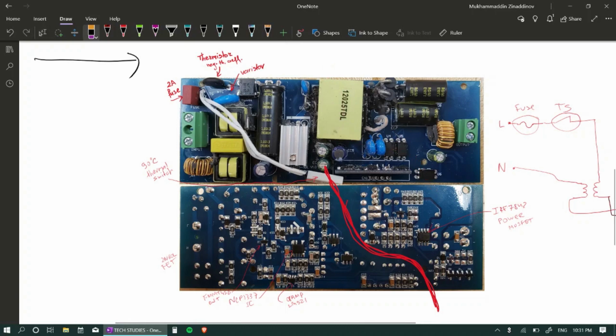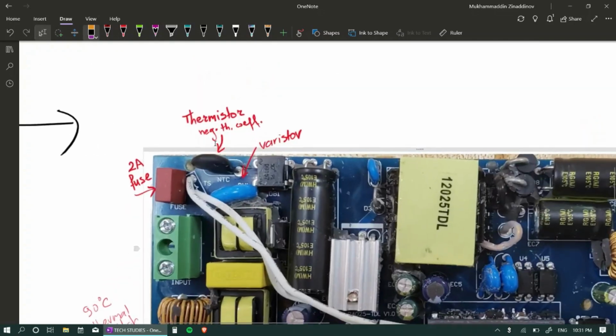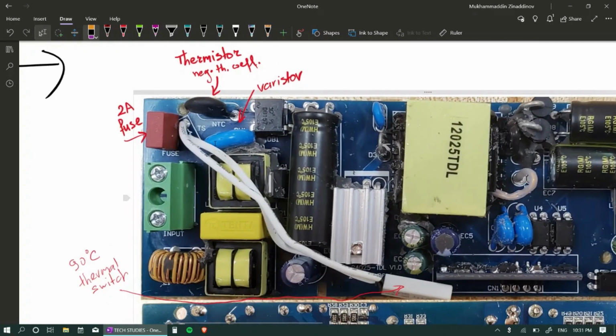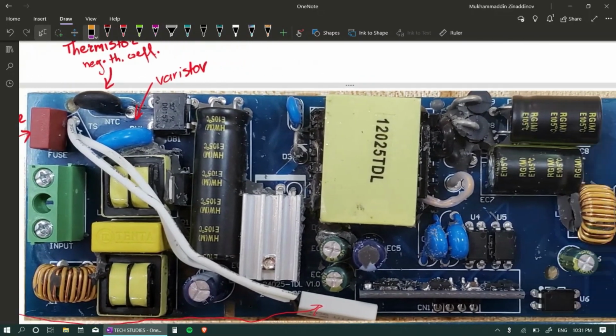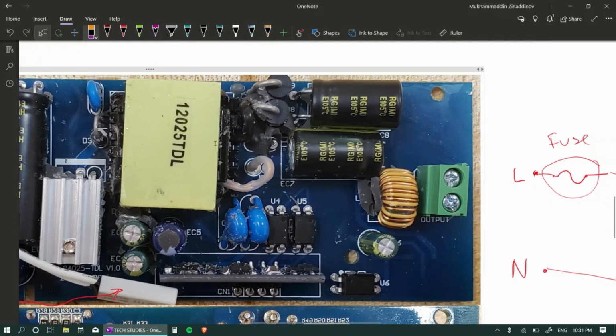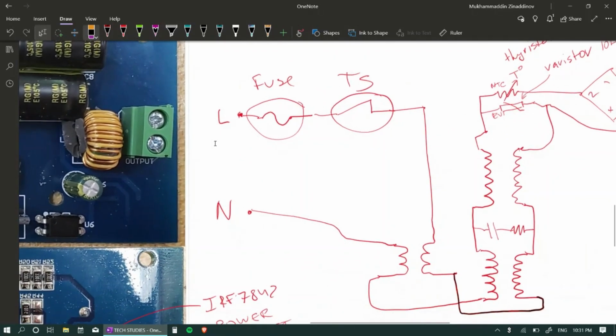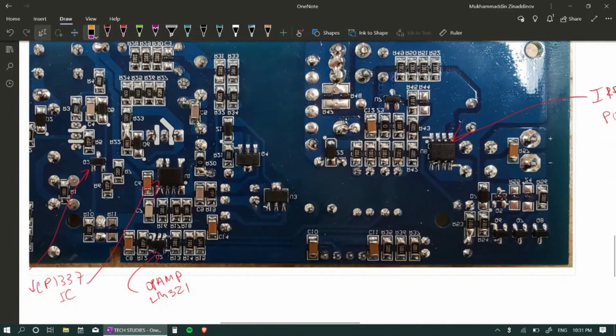So now looking at the circuit, we can come up with an approach for how we're going to start reverse engineering it. We can either start simply from left to right, which makes sense. Follow the traces, and write up the schematic and circuit diagram of the device.